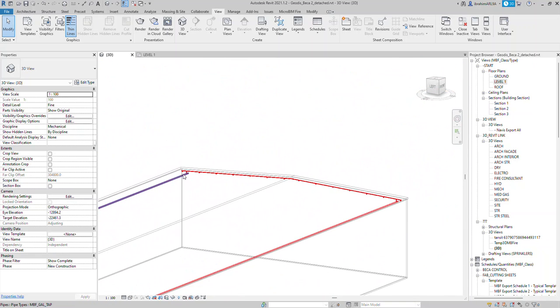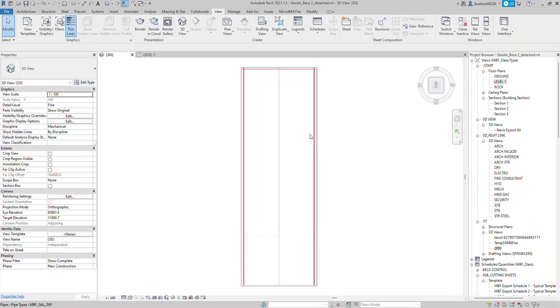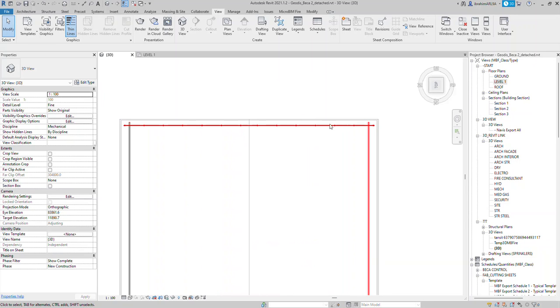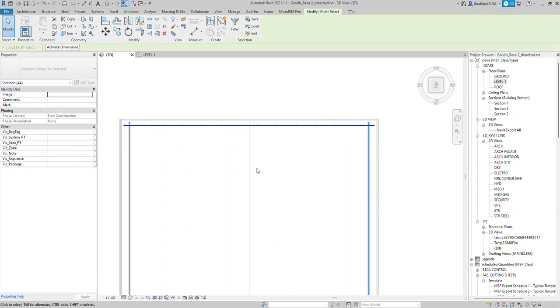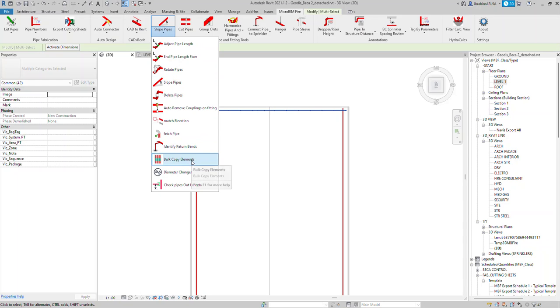Once everything is fine, the first range is okay, I can replicate all of these ranges into a whole network. So I can select this, remove the mains, and then amplifier. You need to use the bulk copy elements from our tools, because the assembly array will break out the assembly after ungrouping. So the best option is to use the copy elements.